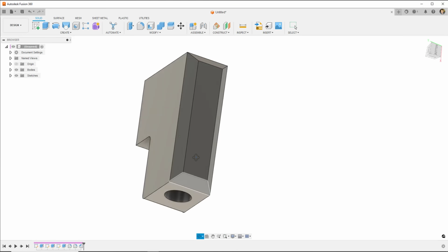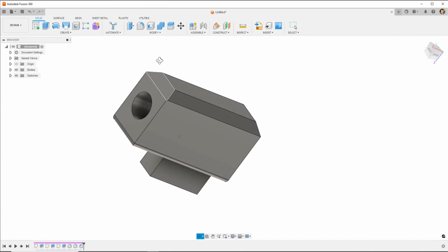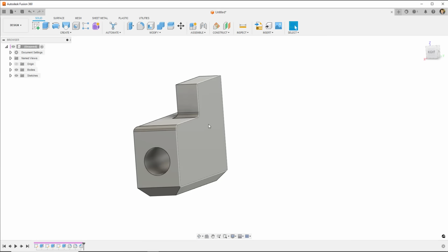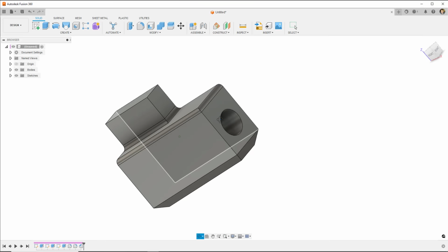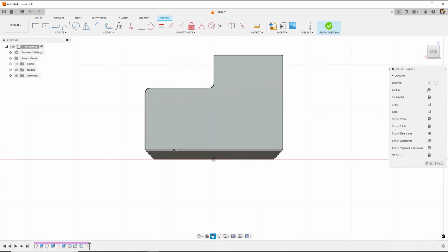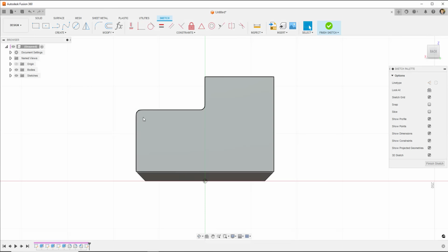Okay, I don't really know what, it's starting to look a bit like a gun, but I don't know what this object is. I'm going to imagine now, because it's got this flat face, it's going to be mounted on something. So we'd need some mounting holes on here. Now again, to do that we're going to go to Sketch, and you could draw circles, which you may be thinking of now. I'm just going to draw some circles, extrude them, that's my mounting holes.